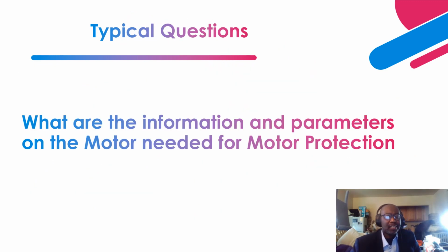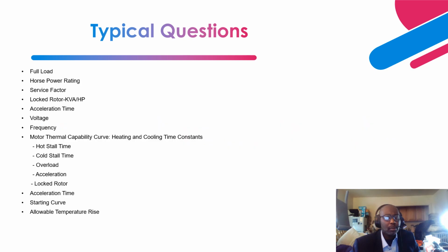Next is a typical question. What are the information and parameters needed for motor protection? As a protection relay engineer, as a discipline relay engineer, you should have a basic knowledge about this, even if you don't do the settings. As a relay technician, as a maintenance technician, electrical technician, as an operator, at least have a knowledge of what are the input information that a protection relay needs to perform the settings of the motor. Okay, so the first one is the full load amps.